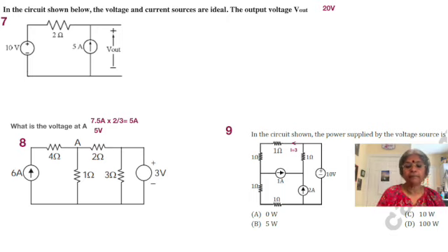Let's say that we have I coming from the voltage source. So I plus 3 flows into the 1 ohm and 1 ohm resistors in series. That creates a voltage drop equal to 2i plus 6, and then 1 ampere goes away.